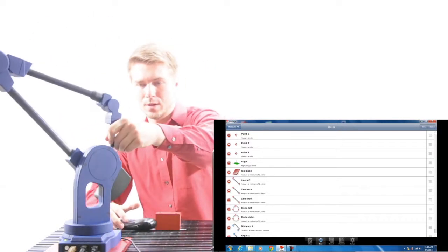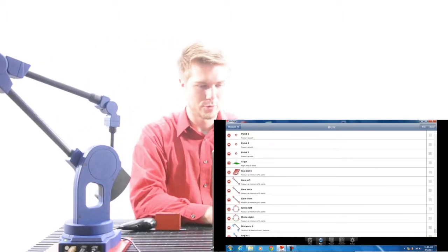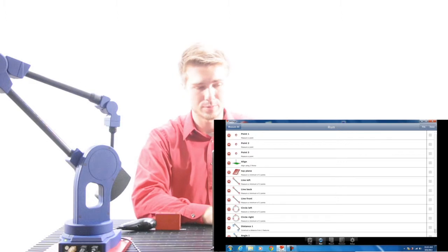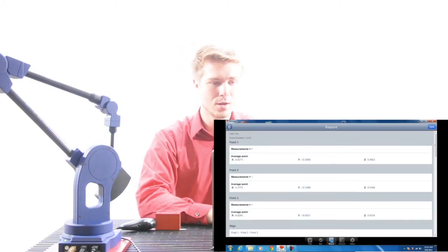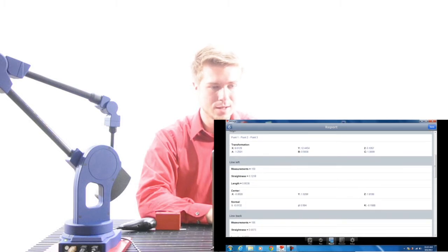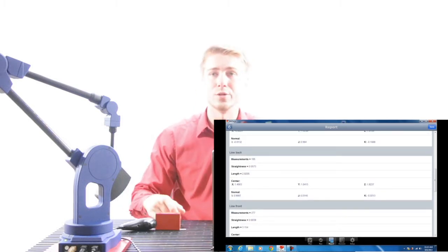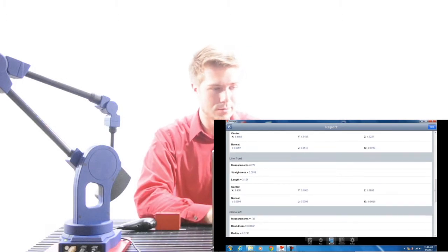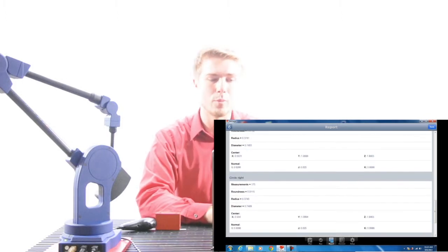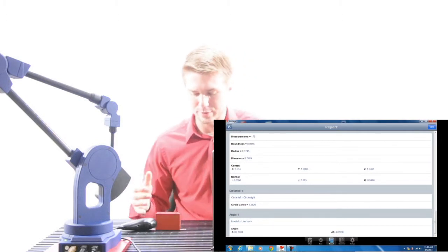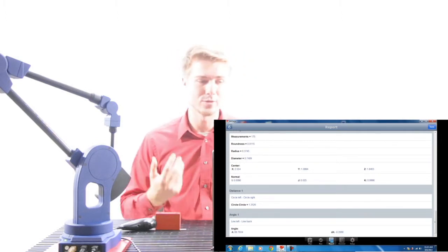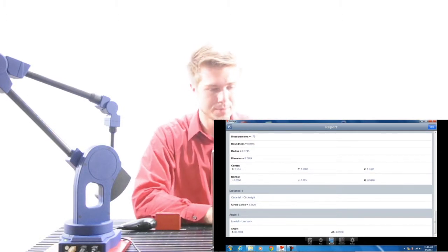Alright, so now that we've gone ahead and ran through our full report, or our full measurement process, we can go to the reporting, and now if you notice as I refresh this, we'll see all those values changed. So now all of our X, Y, Z values have changed in orientation to the block. So now we have a lot more useful information that we can interpret because we are able to set up our origin exactly as we would have it on our blueprints.